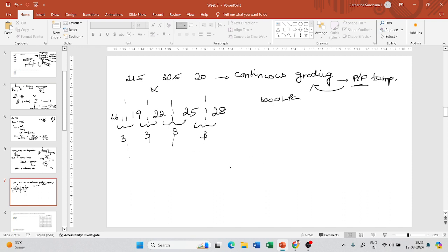Now what the question says is, my bitumen has a value of exactly 6000 kPa at a temperature of 21.5. And now what will you give as the PG grade of bitumen? So if someone asks you like this, you should always be on the safer side, right?